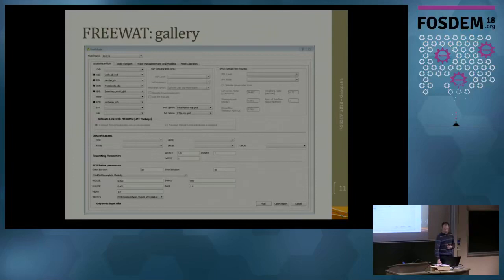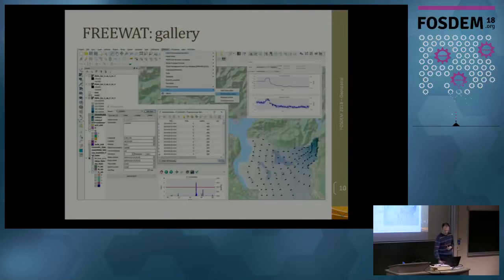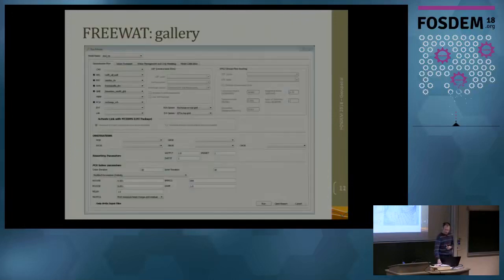The main part of this FREEWAT tool is of course the modeling with MODFLOW itself. So here you can see it a little bit. Maybe you have different options you have to fill in. I guess people who have already worked with a MODFLOW GUI know that you have to insert a lot of data. And this one is related to the packages that your solver needs.